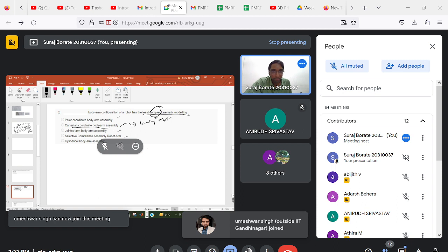So it has only three prismatic joints. One about the z-axis, then the x-axis, and then the y-axis. So it moves up, left, so you can reach any x, y, z position, right? This is the simplest arm that you can see, but once you know the kinematic modeling, if you understand forward kinematics and DH parameters, then I think all of them are easy. Nothing is complex.